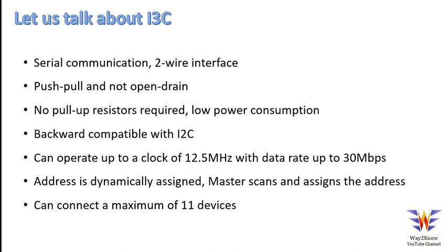Now this is where NXP is talking about I3C along with the MIPI alliance. I3C is also a serial communication interface, which is again a two-wire interface. I3C is coming into picture considering some of the drawbacks that are seen with the I2C. Now this I3C is basically push-pull rather than open drain. That means you don't need any additional external resistor which we use for a standard I2C. That means low power consumption.